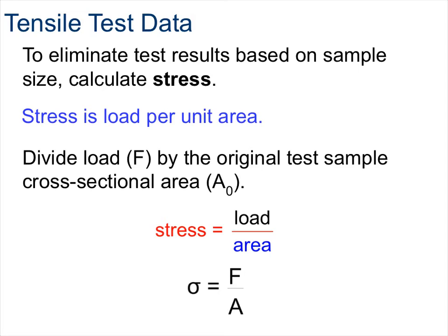When too much stress builds up inside an object, the end result is permanent change in shape or fracture. Given a constant load, the amount of stress that builds up within a structural member will decrease as the cross-sectional area of that structural object increases. Therefore, spreading a force out over a larger area will result in less force per unit area and therefore cause a lot less stress.